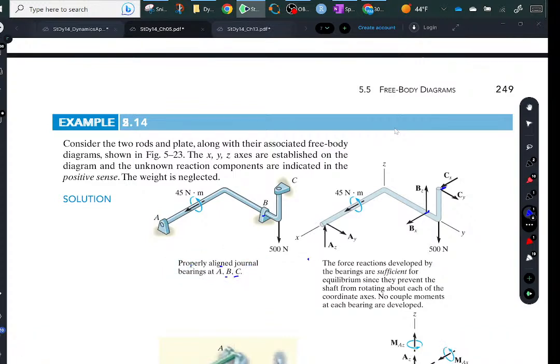And you can have floating bearings, but even if you did put a ball bearing and put a shaft through it, go up to it and try to do this to it, and it will resist your motion. So if you put a bearing, it doesn't matter whether it's properly aligned or not. It can be perfectly aligned, but if you do this, it's going to resist you, and you do that, it's going to resist you.